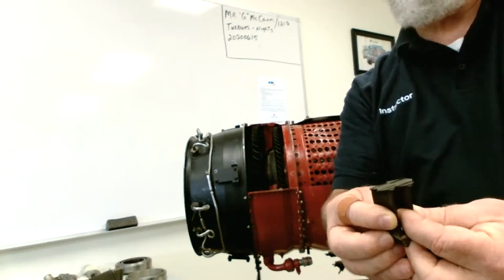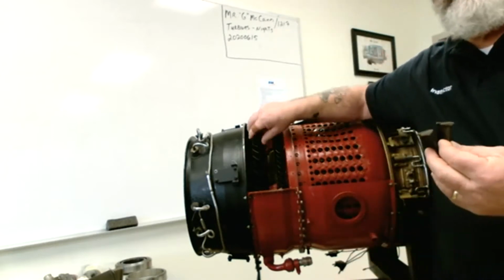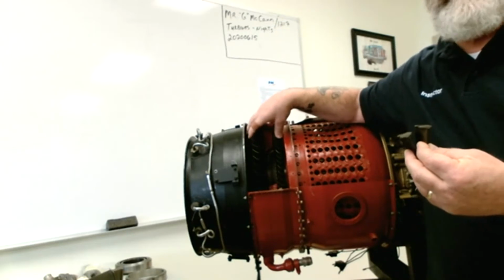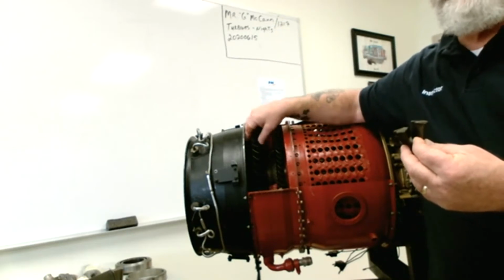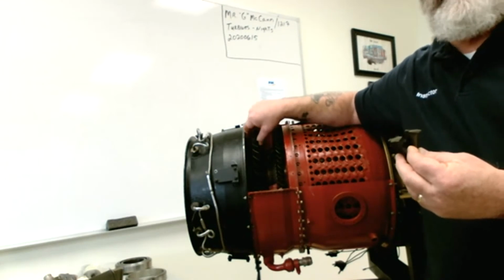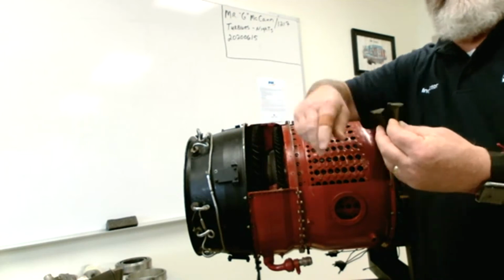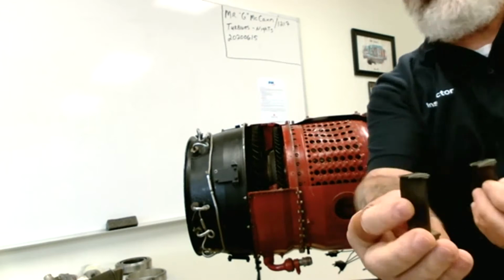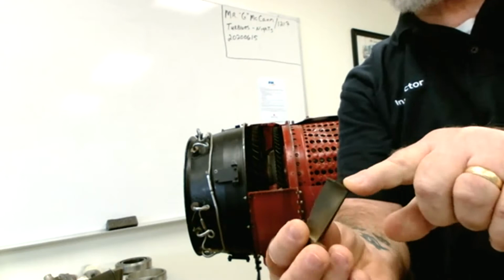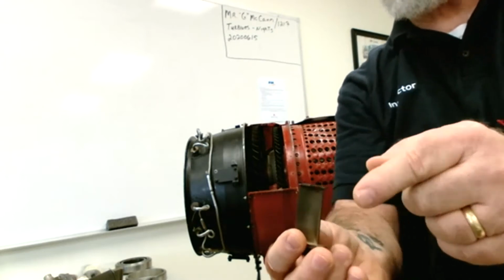Now, like everything else, there's an upside and a downside, right? When a turbine blade increases in length permanently, because remember, this is exposed to very high temperature and very high RPM, the permanent elongation of a turbine blade is referred to as creep, all right? We want to remember that: creep. So you can imagine that with this extra mass at the end of the blade pulling centrifugally, this blade would be more subject to stretch because of this weight on the end of it, right?